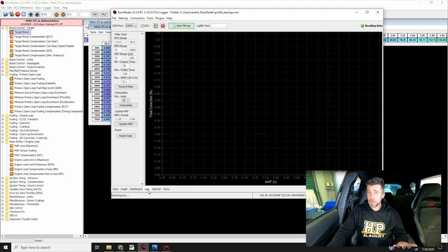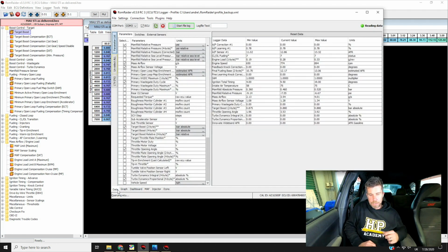First of all, as I've already mentioned at the start of this lesson, we are only learning one package, and we can then use this across multiple reflashing or aftermarket standalone ECU tuning sessions, so that's quite helpful. Personally, I also find that the Mega Log Viewer HD software allows a little bit more control and finesse in rescaling the likes of our mass airflow sensor than focusing on using ROM Raider itself. So we'll head back to our data.